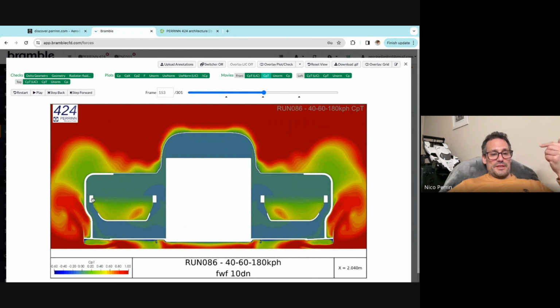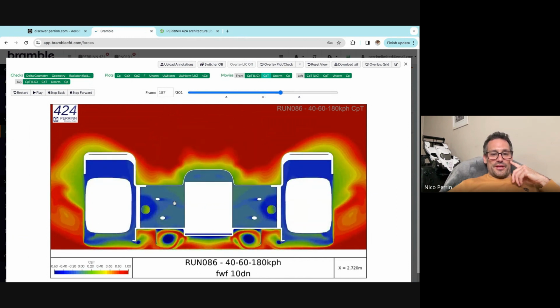And we are measuring through these faces, where the radiator will be. We've got a delta pressure, and we are measuring the mass flow of air going through that. Going to the diffuser area, we've got a very powerful rotational flow. These fences are extremely important. If we remove them, a lot of performance will be gone. And we test, typically I will do 10 millimeters, shift left to right to assess the sensitivity. When I change the top body, I go 25 millimeter steps. But when I touch something under the car, it's more like 10 millimeter steps because it's much more sensitive.